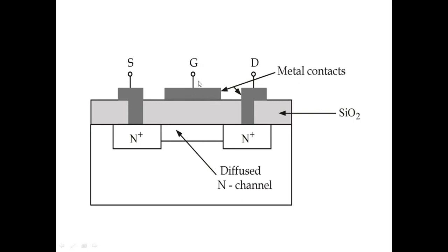Now if too much gate voltage is applied, VGS too large, it can cut off the channel. If the channel disappears, all the electrons enter the p region and electron-hole recombination takes place. So with negative gate voltage, the operation of the MOSFET is similar to that of a JFET. Therefore negative gate operation of the MOSFET is called its depletion mode of operation.